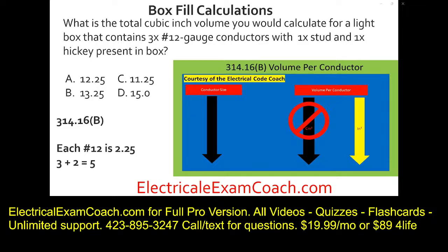the hickeys. Our code states that for each stud and each hickey, they count as 1 each based off the largest conductor that's in the box. In this case, we only have number 12s, so they're going to be grouped with the 12s. So that lets us know that we have a total of 5 number 12s. That's what I meant by we're converting everything back to conductors, and then we can do our multiplication. We take those 5 number 12s, multiply it by the cubic inch volume for 12, and we end up with 11.25 cubic inches, and we would select C.